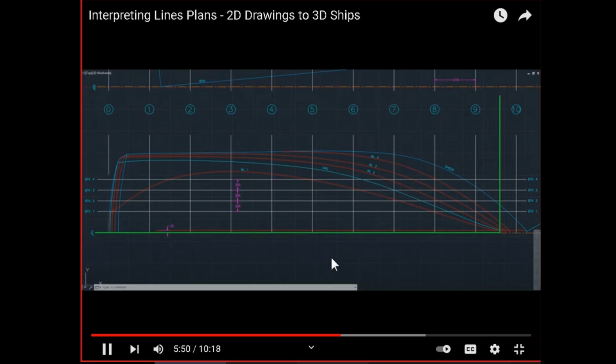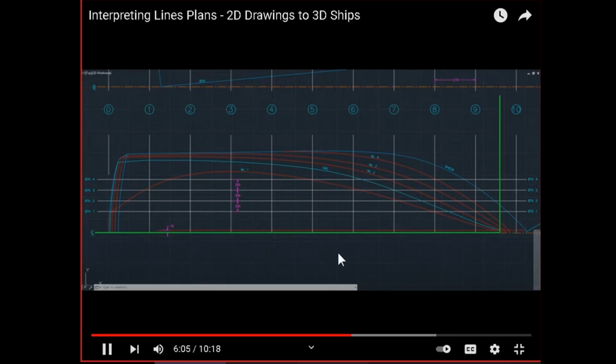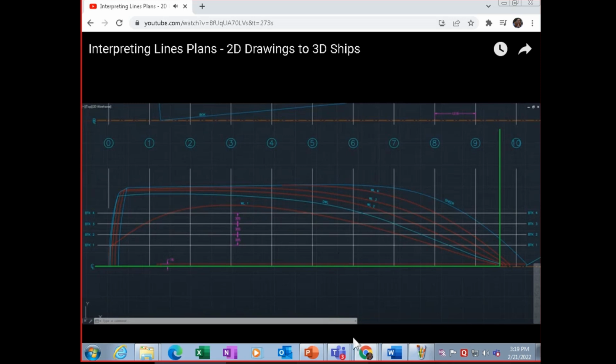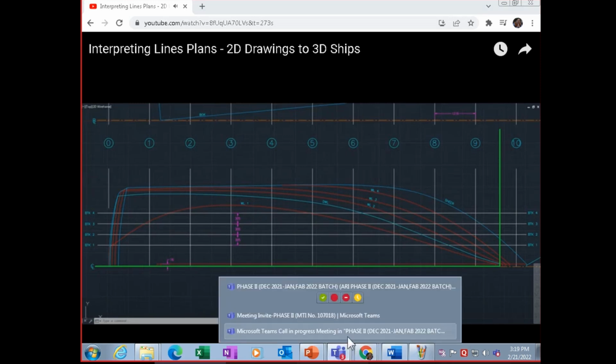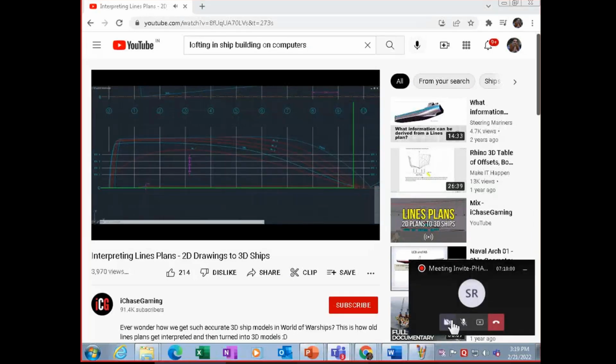And I can also estimate that using something called Simpson's rule or the trapezoidal rule. But that's also something similar, estimating the area underneath. Estimating an area, I would be able to calculate how big that area is. And if I compare that in relation to the length and the breadth of the ship, I would be able to get something called the water plane coefficient.